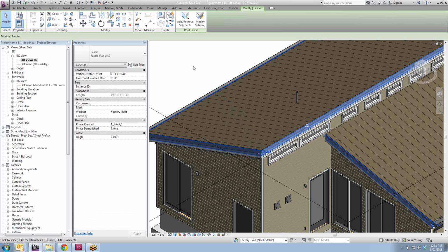And in general, I think we need to model, this is my standard line, we need to model to the level that we need to in order to coordinate elements with one another. And anything at the level of detail to actually build it as a shop drawing or a construction detail, that information exists within the detail itself and not in the relationship of the model elements. So for a door, you need to know what the rough opening is, but exactly how the jamb is laid out and all of that sort of stuff, you look at the jamb detail.